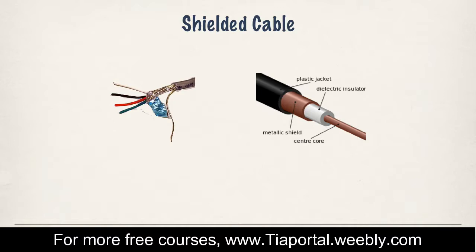So if you're running long distances, it's often advantageous to use a very good shielded cable, as well as sometimes, depending on the distance, you may have to amplify the signal to boost it so that it can make that long distance destination.